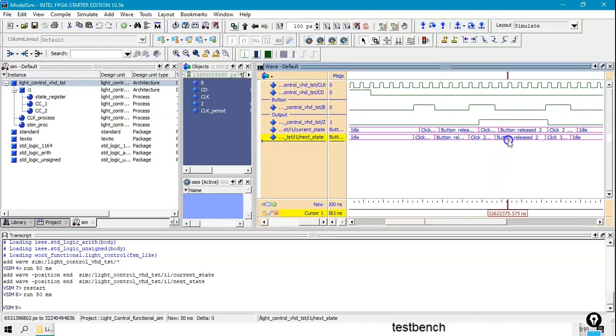So you see now the very idea of the finite state machine running perfectly well. So if this is the functional ideal simulation, the next step is to go and run the gate level as an extra thing to see how it works for real. Okay, so this time you can imagine that you are simulating the RTL circuit, and you see the current state and next state, and the levels are precisely from this point of view of the high level description by means of a state diagram and the like.